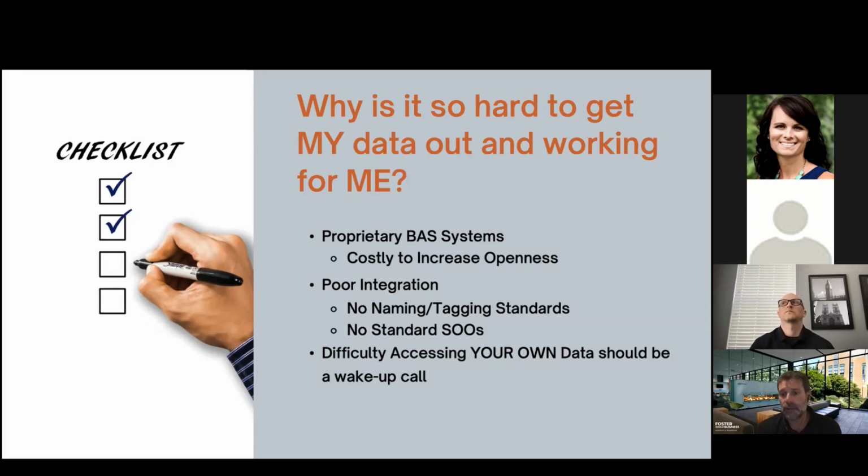Let's go to a BACnet protocol, and you can utilize your service contract that you already have with that vendor to start building that database, so that it can communicate on the trunk. Then you're building those key foundational pieces so that you can actually have a fault detection layer above your building automation system.